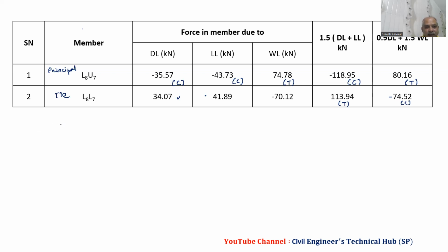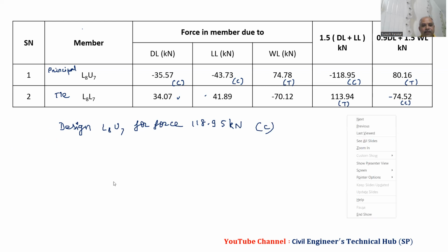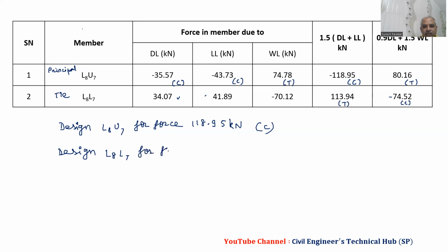That means we have to design L8 U7 for a force of 118.95 kilonewton, and that is compression. And then we have to design the other member, L8 L7, for a force of 113.94 kilonewton, and this is for tension. So now we will first design L8 U7.